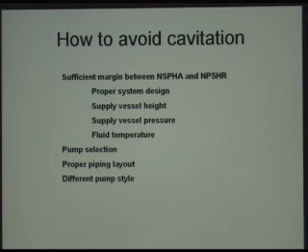If you can push your vessel up higher, that adds more static head, which will increase the pressure at the pump. I don't want to change my static head because that is constant. The installation can change it. Okay. Well, there's some other alternatives then that we can talk about, what we can do.